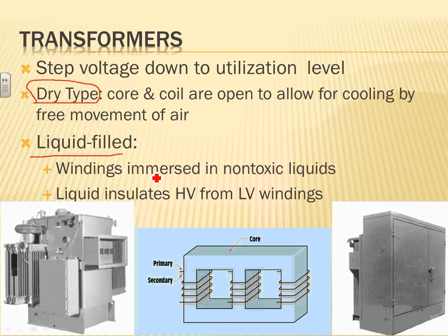Do you guys use liquid type transformers? A lot? Not a lot? A few. In the medium voltage world, you use a lot of them. So when would I use a liquid type transformer? If you need more volt amps, more power out of the transformer. So that's what I thought. Step down, the dry type transformer. Most of us will deal with the dry type transformers.